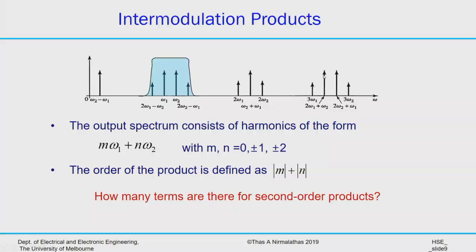So how do you know how many of these things are going to be in a circuit? It really goes back to that nonlinear transfer function and the gain that you have. Remember, the nonlinear transfer function tells you A1, A2, A3. If A3 is very large, then it's going to produce a lot of components. If A5 is almost zero, it's not going to lead to more components. So it really depends on the nonlinear characteristics and how much gain you're putting in later, in order to know how many of these components are going to be produced.